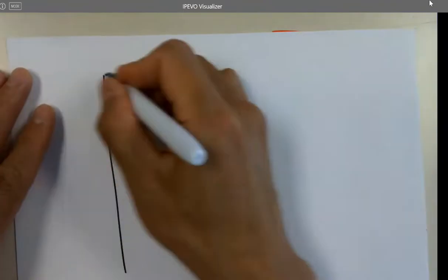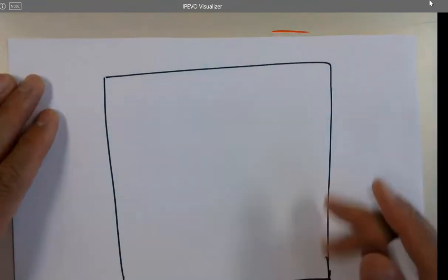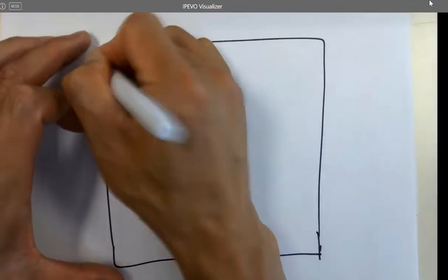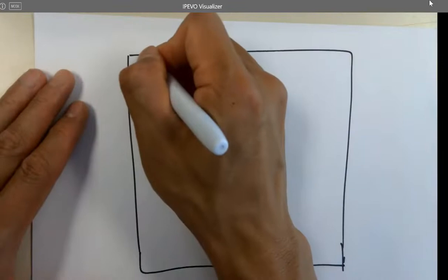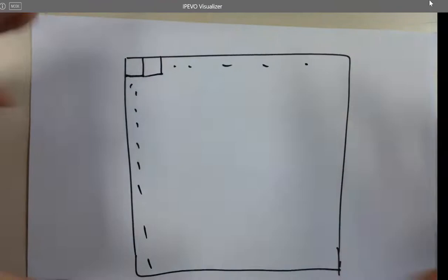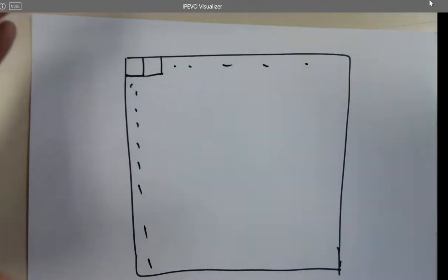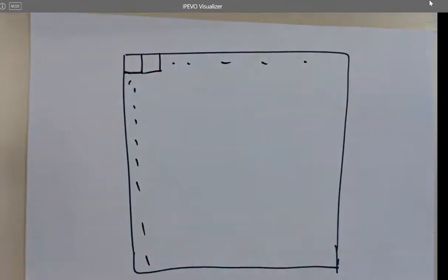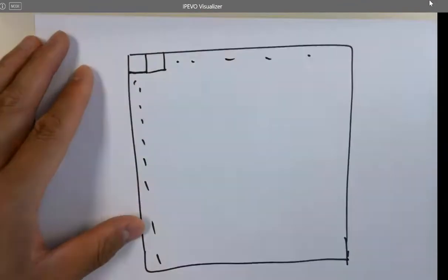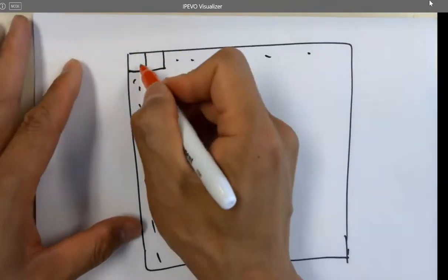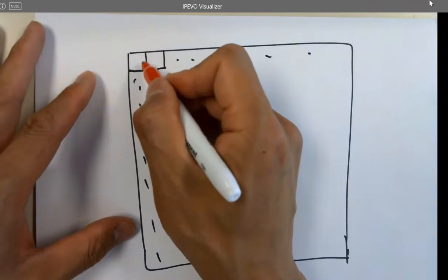Okay, I'm talking about a camera sensor. So for example, this is a camera sensor, right? This is whatever the chip layout. You open the cover, you can see a chip. And here's one pixel. Okay, here's one pixel. And here's another pixel. You have many of them to capture an image, right? But more pixels means better resolution, more dots to resolve that image, okay? And so the aspect ratio defines the footprint of the photodiode versus the whole area of the pixel.